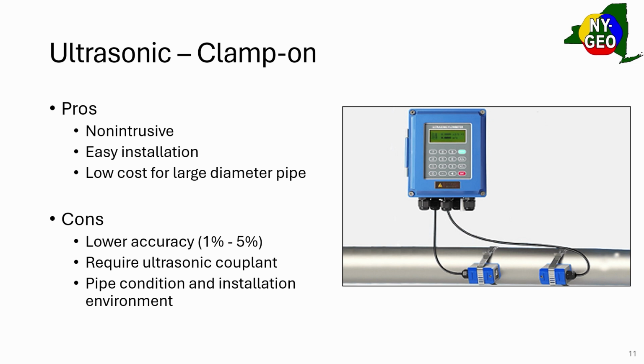However, due to that sensitivity of placement of those transducers, it is lower accuracy. They also require an ultrasonic couplant, which is quite messy, and the pipe condition and installation environment affects the accuracy of the reading and the communication between the two sensors.